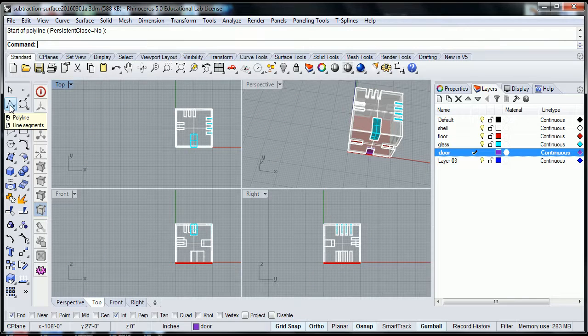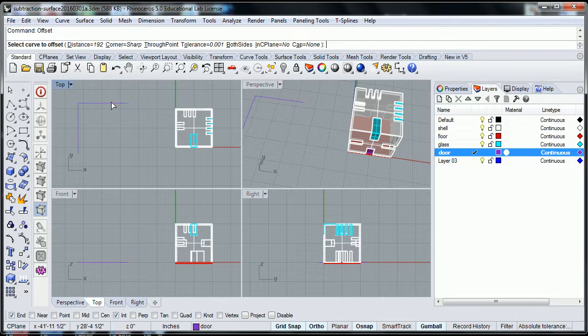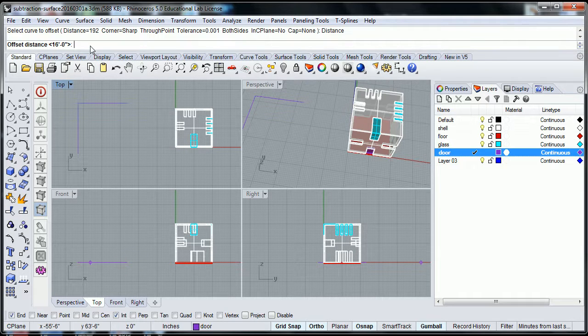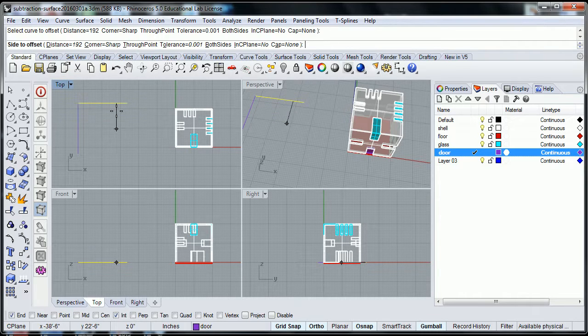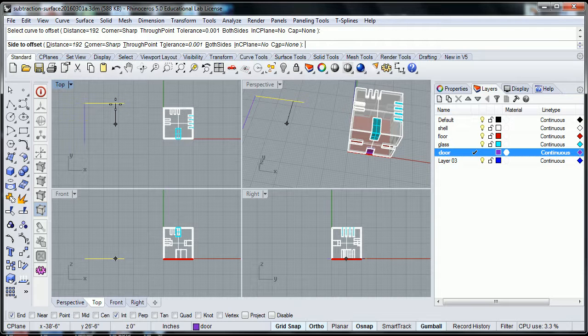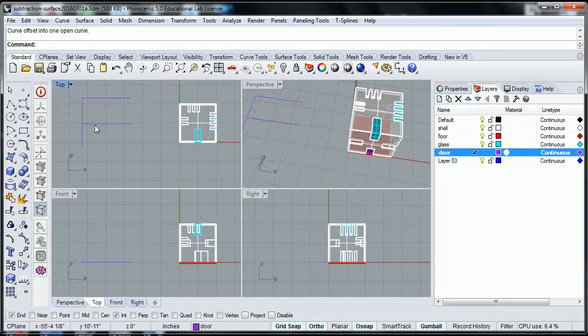I was supposed to select the line segment so that all the lines are individual, and then select the offset, and it is in the 16 feet. Enter. Everything else is good, so we'll select that, and notice that this little line, whichever way the cursor moves, the line comes with it. That is asking you which direction you want to offset the line to. So I'm going to offset this line towards the down, and there I have the 16 feet copy of that line.